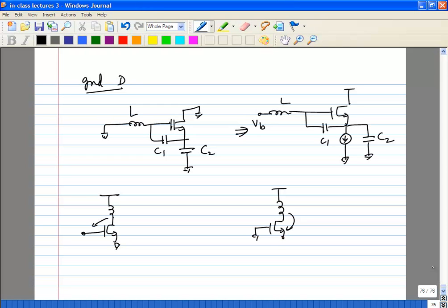You know that the current and voltage have to be in phase because the resonant circuit is completely resistive at resonance. Obviously if you feedback this way, the current and voltage are not going to be in phase. So this is the right way to do the feedback. Okay, how do you do the feedback? You can do it several ways.